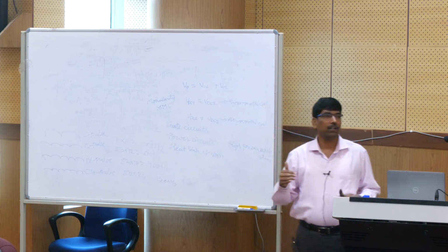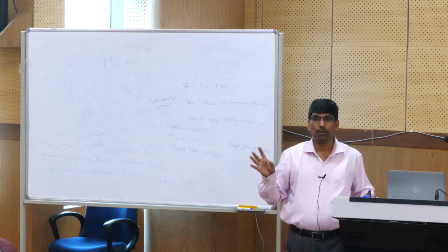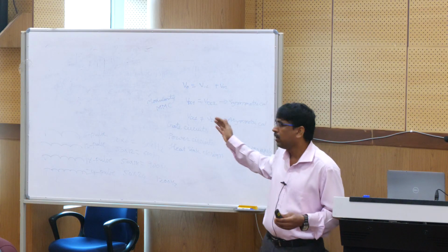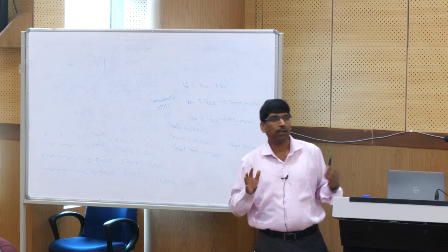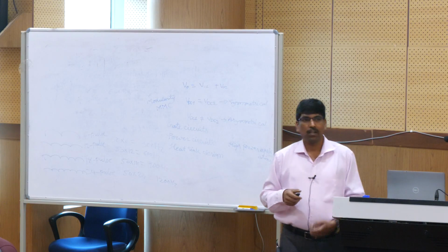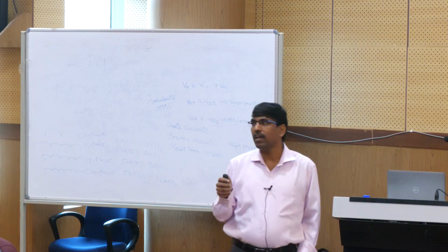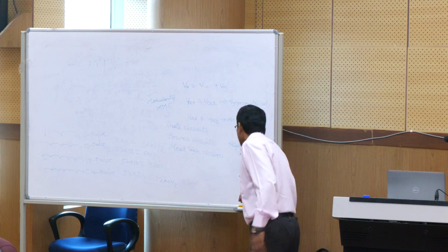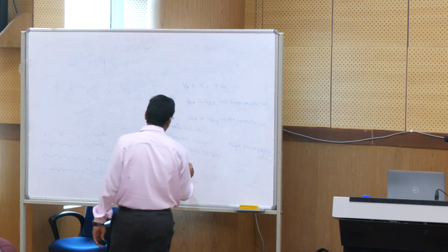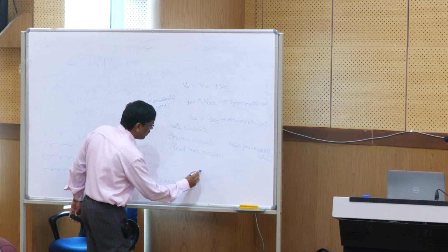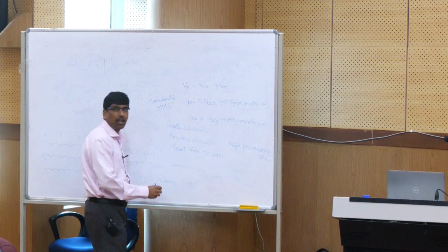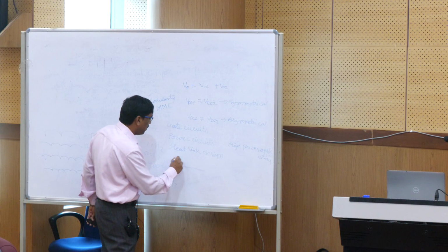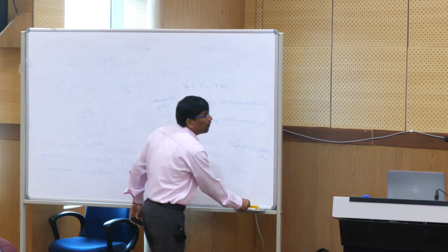You will smooth it, but to smooth this kind of harmonics, the ripples, what are we going to do? Yeah, that is the DC link capacitor we will make use of. After incorporating the filter, you will get a pure straight line, with the magnitude above the 0 level. This is what you are going to make.